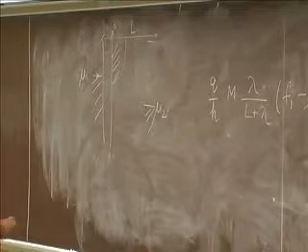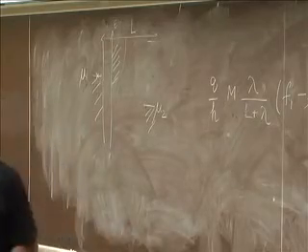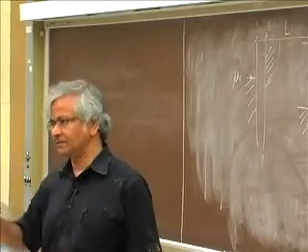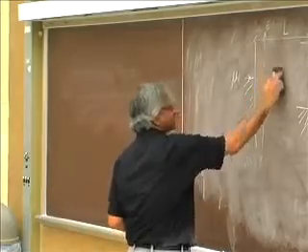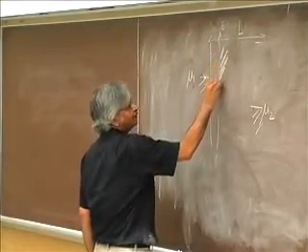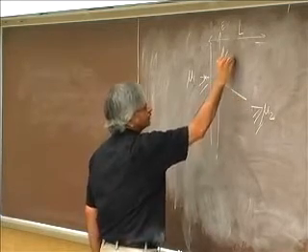And this is where the way I think about it is that this is something that kind of requires you to go beyond a point channel model and think about what is happening inside the device, the spatial distribution of things. Because if you looked at the density of states inside, it is sort of like you have a density of states here, but then because of the electric field, it is going down here like this.